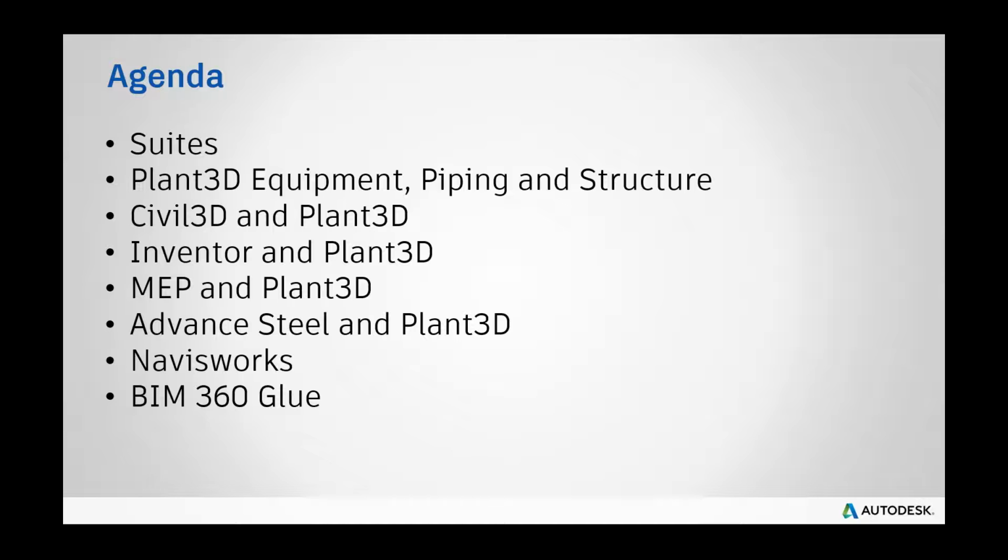And then finally, the last 2 points, which are the basis of this collaboration webinar, are Navisworks and BIM360 Glue. Navisworks, if anyone isn't aware, is inside pretty much all of our suites. Depending on which flavor of suite you get, it will be either Navisworks Simulate or Navisworks Manage. So we're going to look at Navisworks Manage today. It contains clash detection, timelining, and just walking around and reviewing the model. The difference between Manage and Simulate is basically just clash detection.